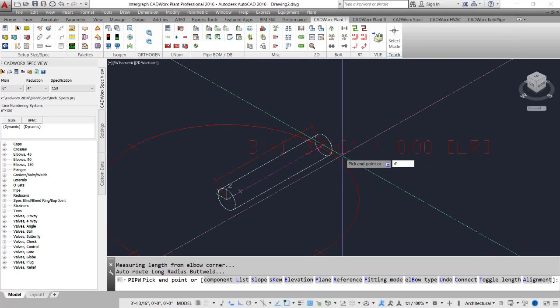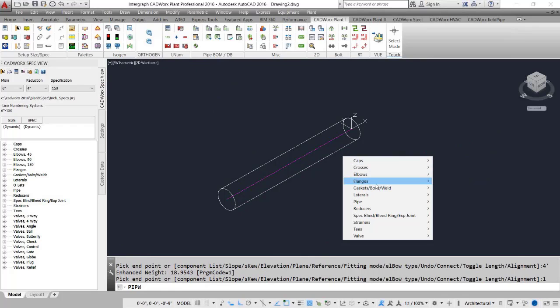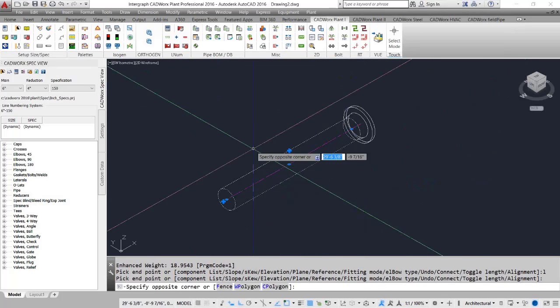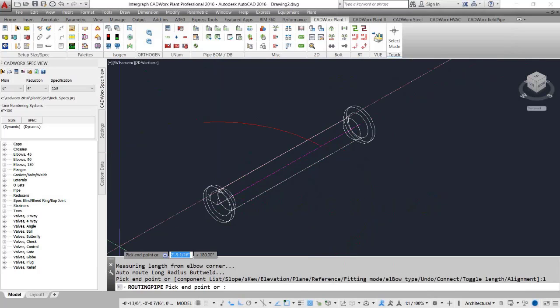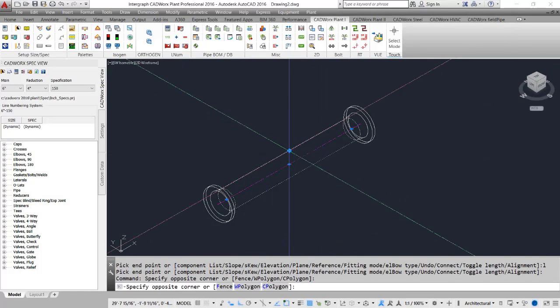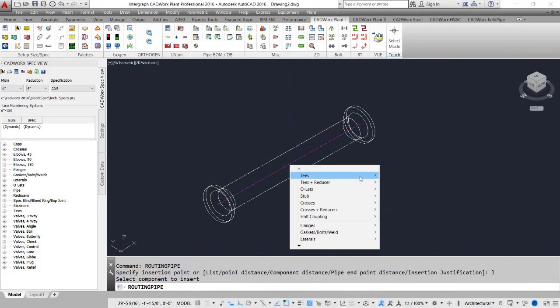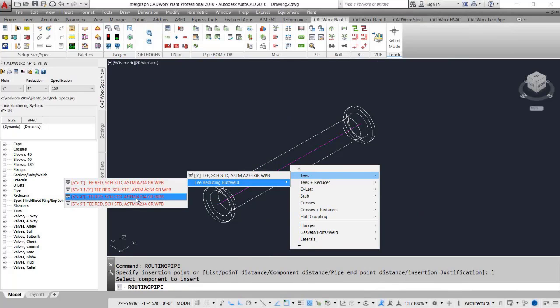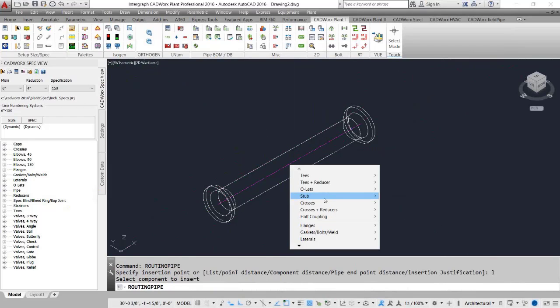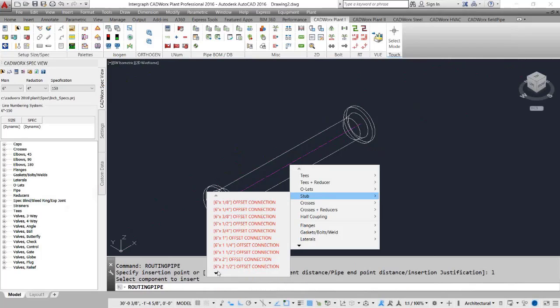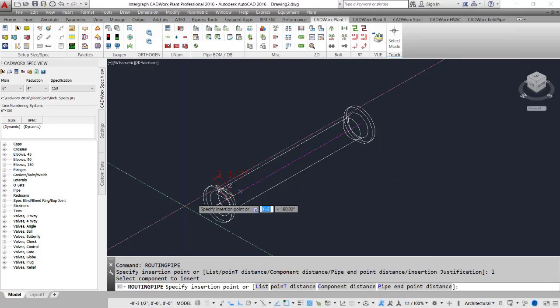So here I can come out and I'll just go 4 feet and we'll list out and go get a flange. So this is going to be the flange connections for our flow meter. Okay, and what we'll do here is just create some geometry to take up the proper real estate for the flow meter here. I'll just use a 6x4. We'll put some, actually, you know what? That would create fitting makeup. Let's avoid that. Let's do a stub. And I'll show you why we're going to do that here in just a second. So we're going to go 4x6 stub in connection.